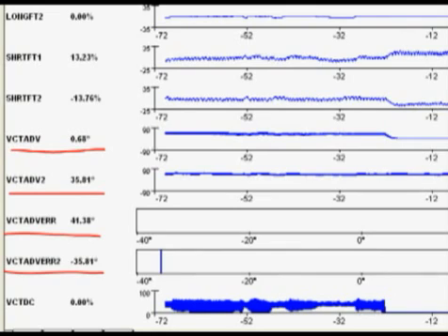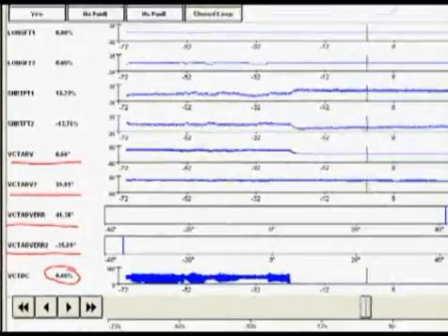At the time that we have these offsets in VCT error, we have a duty cycle of 0 for the solenoid that controls each cam. We can only put so many PIDs on the screen, but they're both at 0. So what is going on?